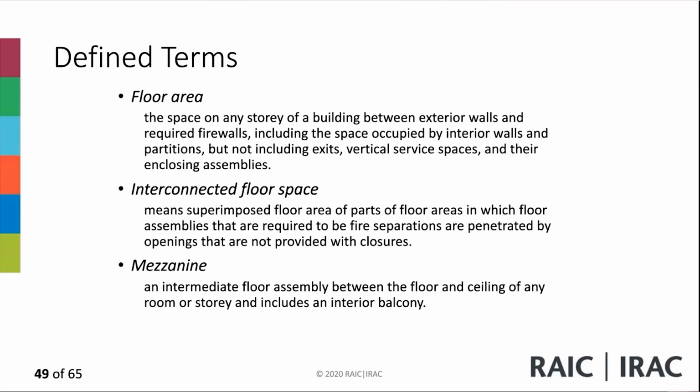First of all, a rooftop enclosure. Take that note. Provided for elevator machinery, a stairway, or a service room used for no other purpose other than for the services for the building, they shall not be considered as a story in calculating building height. So remember that one. So people are familiar with it probably. So when you're calculating building height and number of stories, do not count those service rooms.